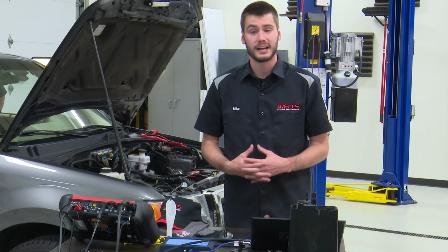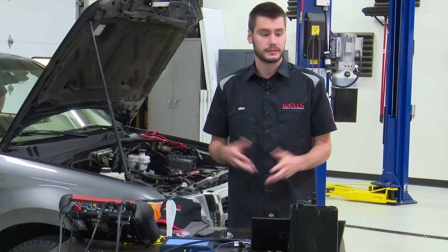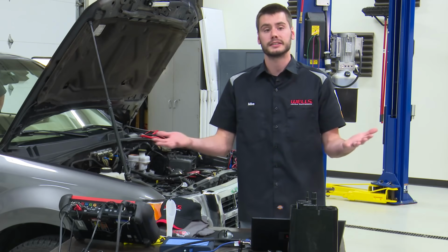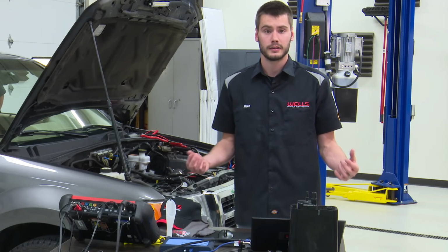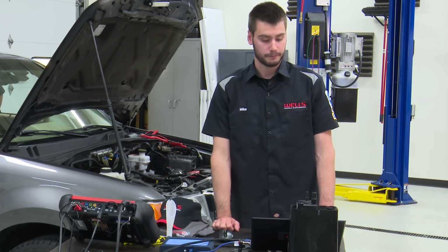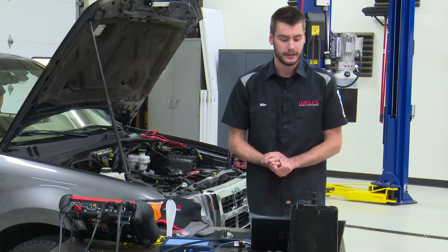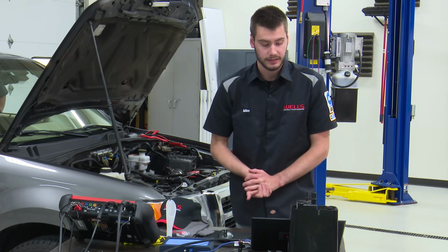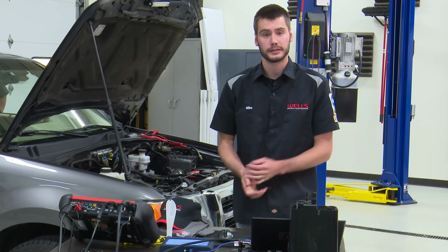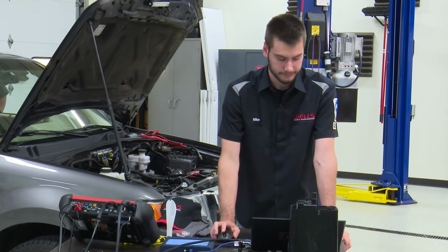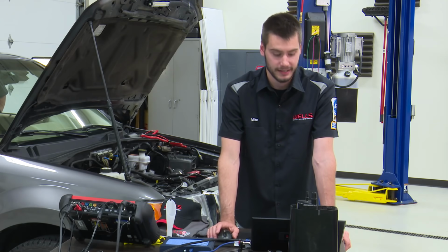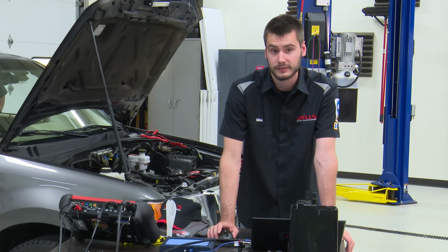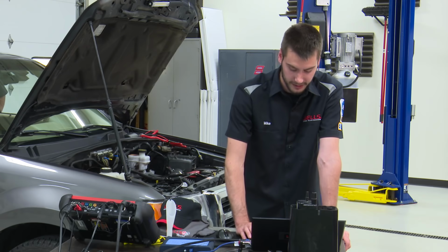You don't want to be pumping oxygen into there because oxygen, fuel, what do you need? You need some sort of ignition source, and you have an event, we'll call it that. So you don't want that to happen, so you're supposed to use pressurized nitrogen, but how many of you guys have a nitrogen tank for EVAP checking? I'm honestly curious to see if there are people that actually have it.